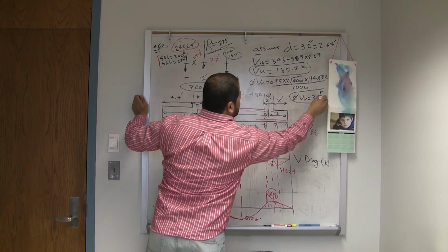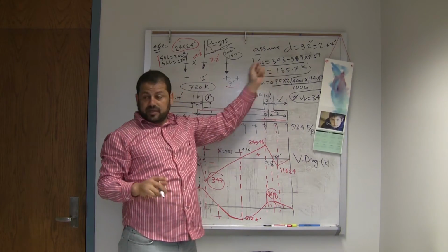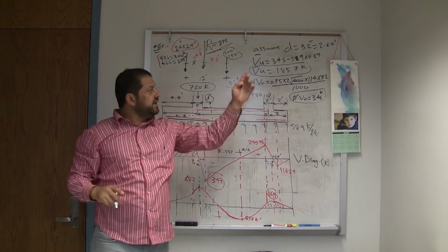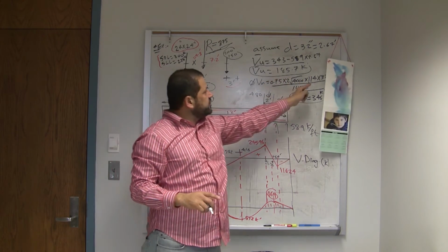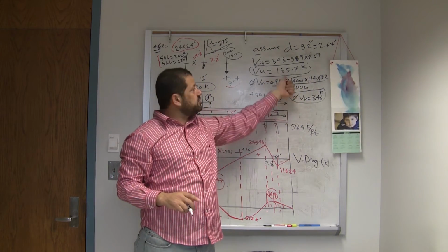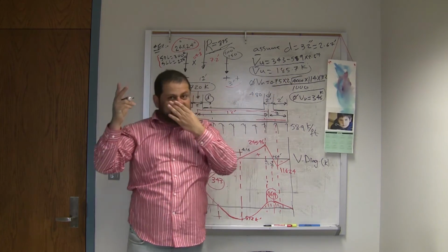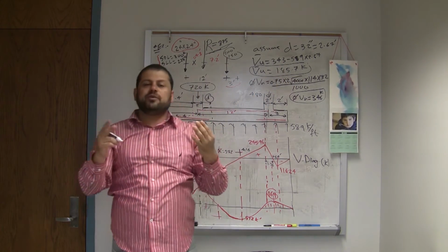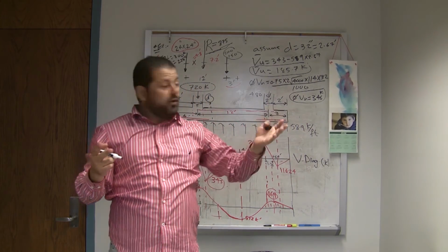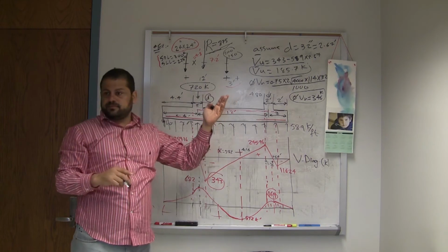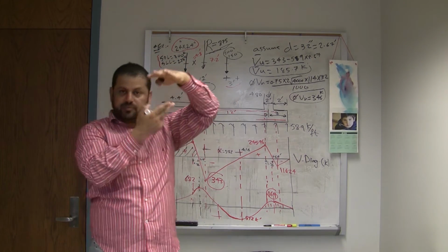This is kind of high. So what I'm going to do is drop D. Remember, when you drop D, this will drop and this will increase, so you have to be careful. That's how you do it, trial and error. I'm going to assume my footing will be 2.5 foot, which is 30 inch. Actually, we can try a 2 foot depth of the footing first.